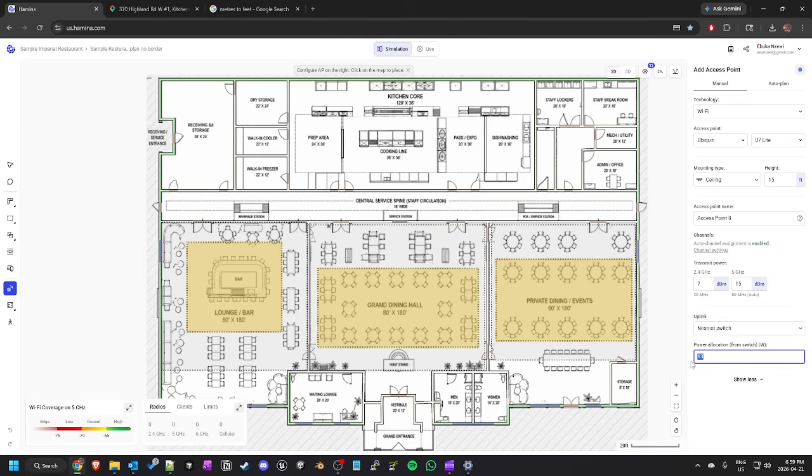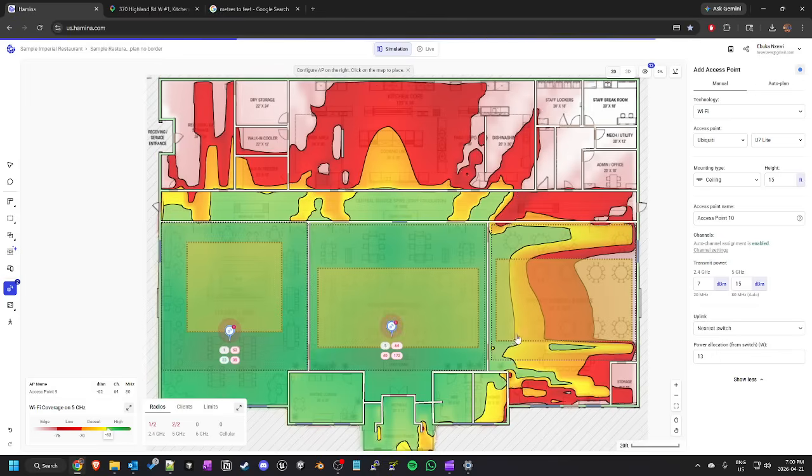In this case, for me, I think 13 watts is kind of high. Most APs would operate around 7. Well, technically, some APs' max operation will be around 15, but their day-to-day operation will be somewhere around 7 because it's based on client requirements as well. But let's play it safe. Let's assume it's 13. Let's keep the default. All right, just play it safe. I'll place the APs on the floor plan now.